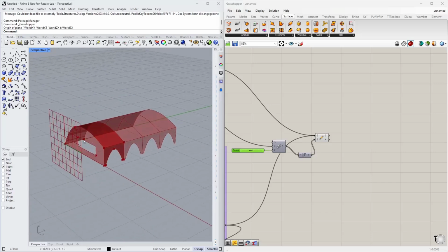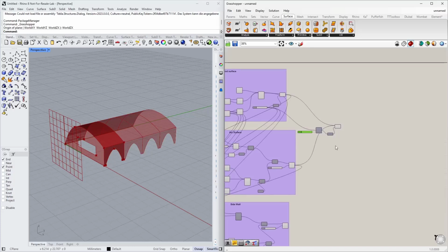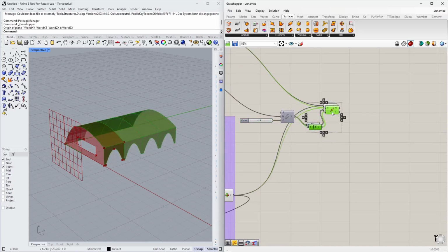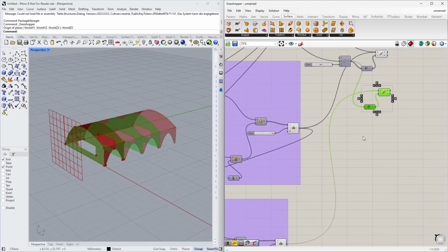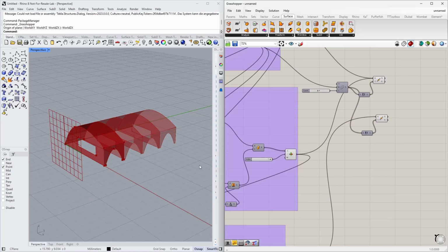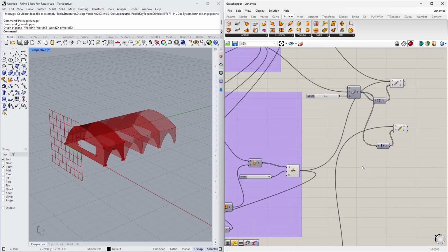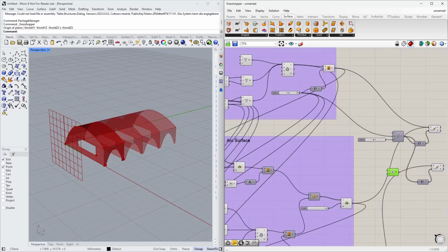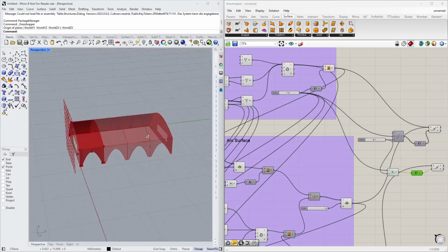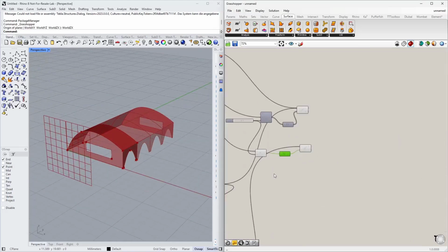Now I only have to copy the front surface to the end. So I use another move command for that. And I copy this surface. Of course, not multiple times. I only want to have it one time. And then the end and the distance for this is actually a little multiplication. We simply multiply the extrusion length with the amount of copies. And that's the length that we need to copy it from the front to the end. Okay. So far so good.